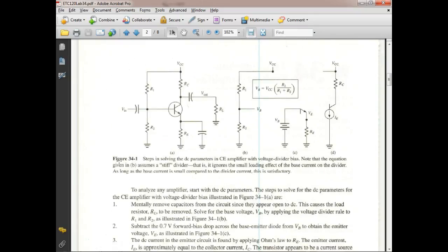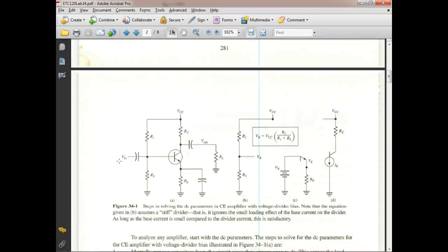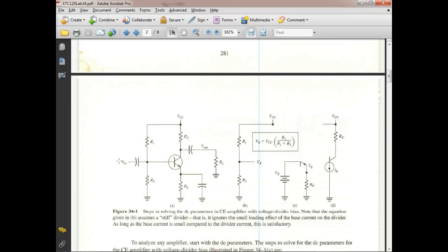They said the advantage of a full wave rectifier over a half wave rectifier is the pulse frequency is 120 hertz on one and 60 hertz on the other. What in the world is that advantage? When I'm looking for a power supply, what am I trying to get? I'm trying to get volts, right? You understand? So for the same secondary voltage, a full wave will give you twice the voltage as a half wave. Y'all understand that?